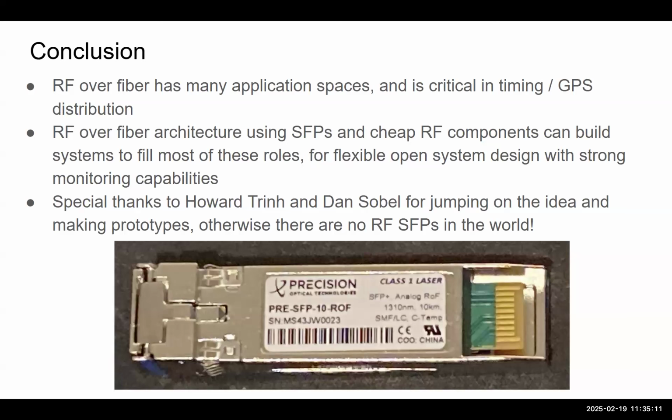It still meets that standard even with the analog output, which means monitoring is implemented over I2C. So you can monitor the signal strength and temperature. It does not have a receiver, so that has been eliminated, but all transmit parameters are monitorable, as defined by that standard.